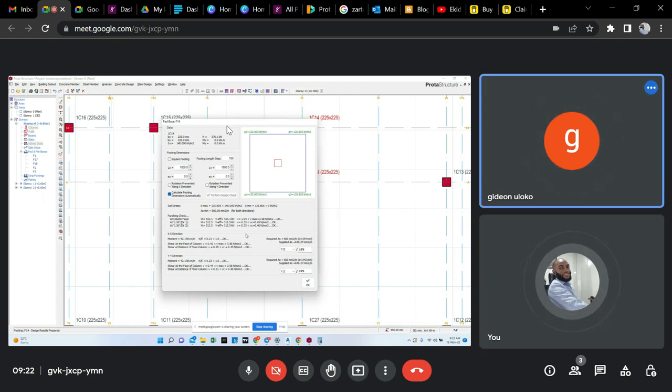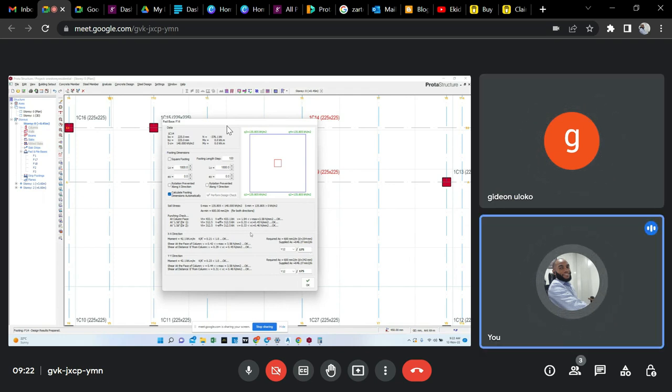But if you go and use 250 depth, that means you can increase your spacing of the reinforcement, to be Y16, which might increase the cost. Because with this right now, I think this one of 1.8 and 300 and having 175 spacing will be a bit lower in cost than going to use diameter 16, Y16, 1.9 and 250 depth. So I think this is okay. So now click on OK if you're going to choose this for a combined footing.